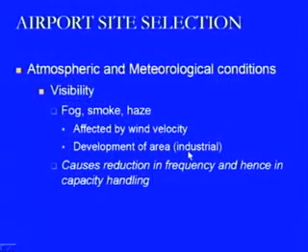If it is an industrial area, then there are more chances of smoke coming out of it. And if the wind is blowing from the industrial side towards the airport side, then the smoke will always be coming to the airport side. Whereas, if the airport is on the windward side and the industrial area is on the leeward side, then the wind will always be moving away from the airport and there will not be any problem of smoke.